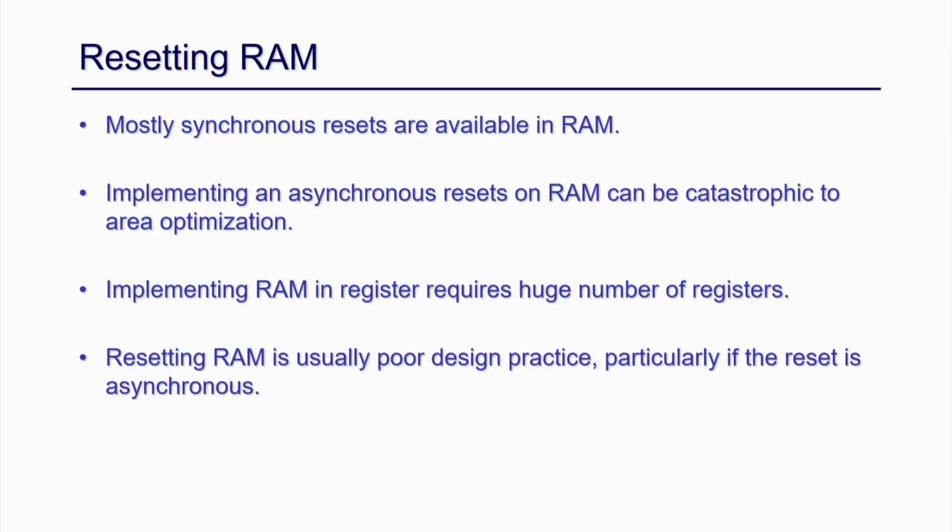Okay. So, now we are going to talk about the RAM. We have discussed shift registers, we have discussed DSPs. Now, we are going to discuss the pin configuration of RAM. RAM has a synchronous reset; it does not have any asynchronous reset or asynchronous set. Okay. So, if you use any asynchronous reset in your design, it has a bad, catastrophic impact on